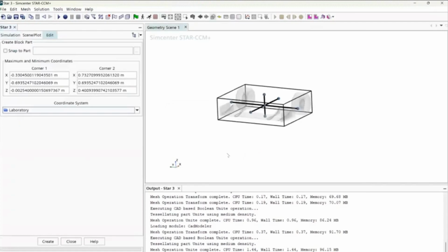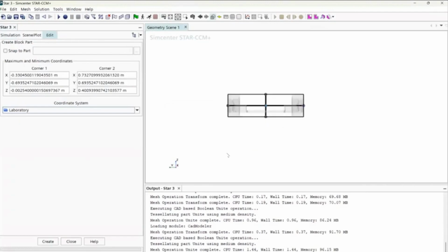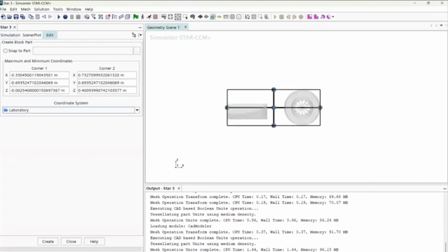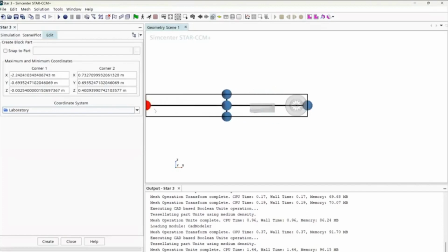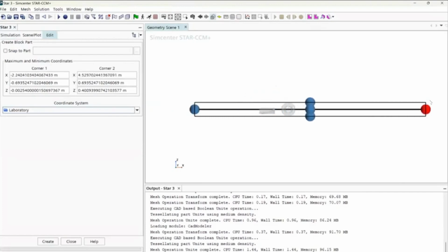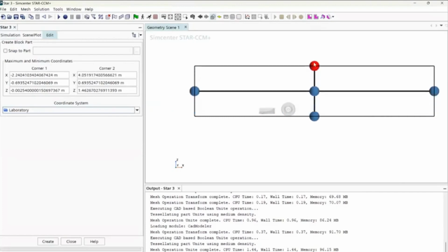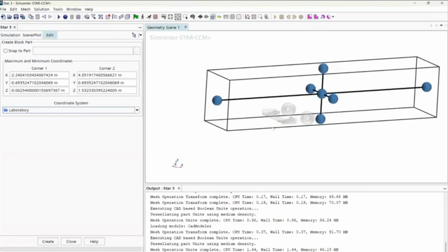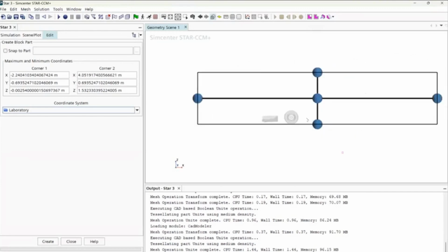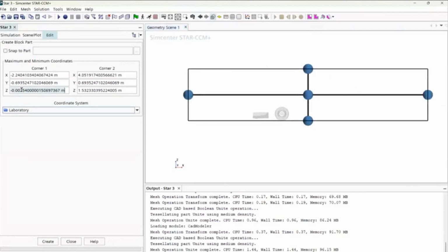And I'm going to talk now about CFD basic principles. Now, usually you can be making it bigger. The domain should be bigger than what I'm telling you, but the minimum size it can be is whatever this length is, 4 of those lengths in front, 8 of those lengths behind, and 4 on top. And of course, for this simulation itself, the ground is very important. The ground affects the front width. So we're not going to mess with the ground. We want to be at 0. But, well, 0.